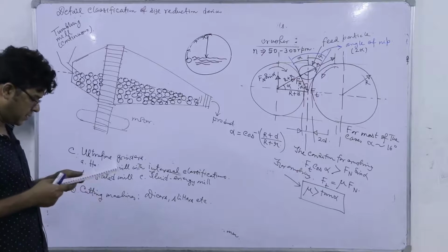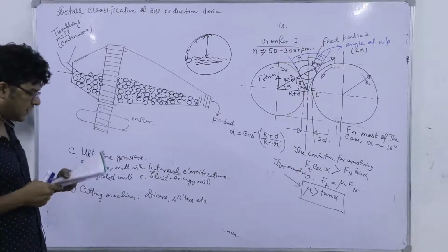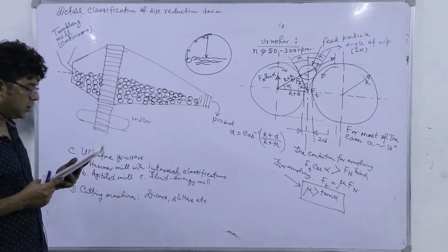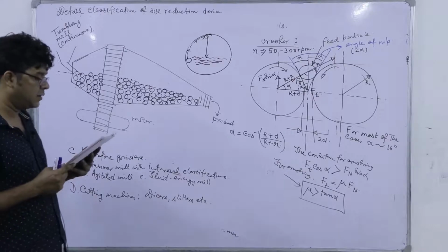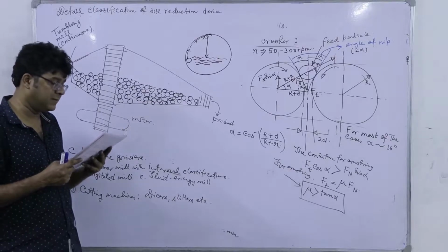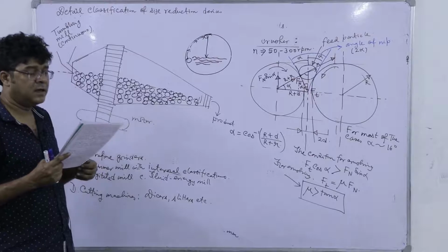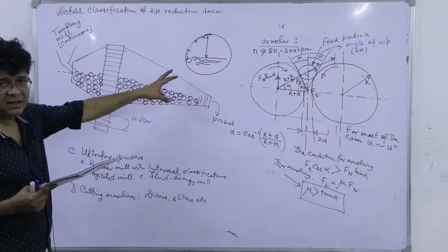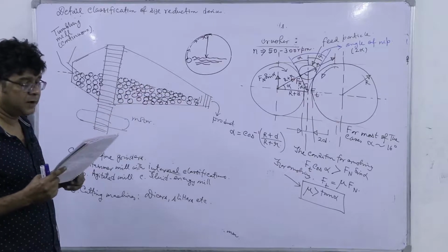Let me describe some of the salient features. The load of balls in the ball or tube mill is normally such that when the mill is stopped, the balls occupy about half of the volume of the mill. I have discussed it. The void fraction of the ball mass when it is at rest is typically around 0.4, a property of spheres.